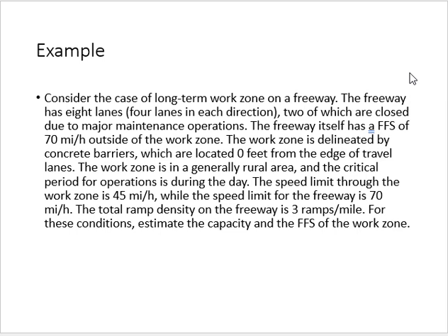Okay? An incident happened, there was an accident on the highway, the police came, maybe half an hour, everything is clear. No adjustment factor, right? But if there is an incident which blocks the highway for the whole year, obviously then I need an adjustment factor. Clear? So adjustment factors are not for short-term conditions. Clear? Okay. So the example says a long-term work zone, so we should apply an adjustment factor.